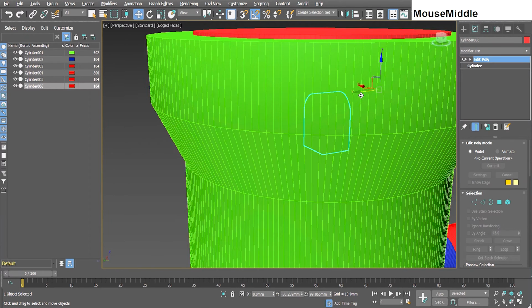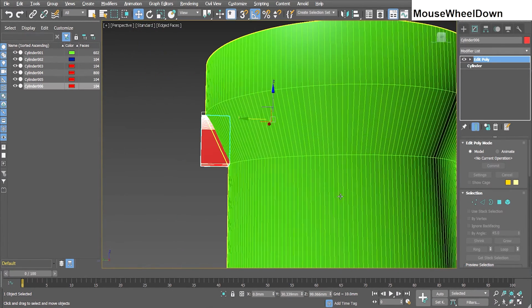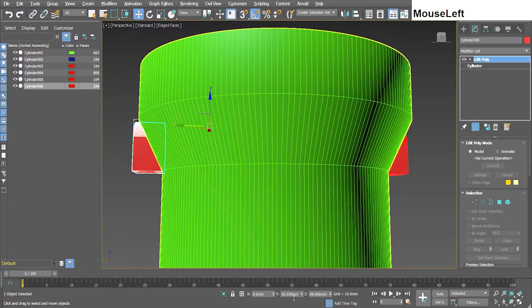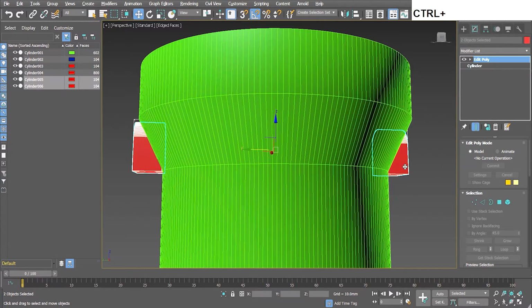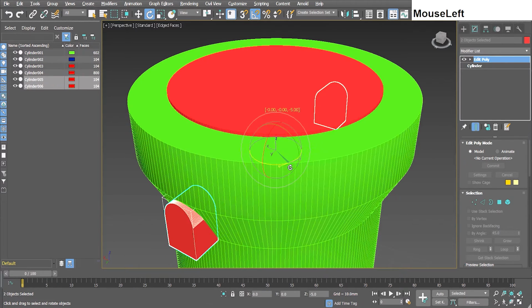And all I have to do is move it on this y-axis. And I'm going to select this original one, copy that number with Control-C, and paste it over here with Control-V. Now they are perfectly the opposite side of the center apart from each other. That matters because when I select both and switch to this rotate tool, I'm going to hold Shift as I rotate them along this axis here.